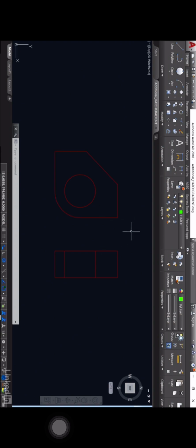is a sectional view. Now normally you would use something like hatching or cross hatching to highlight where you've cut a section through a particular object. So this is the sectional view on the right. So make sure you're using the hatch layer here in the layers panel in the home tab on the ribbon. The hatch command itself is in the draw panel, and I click on the flyout here and select hatch.